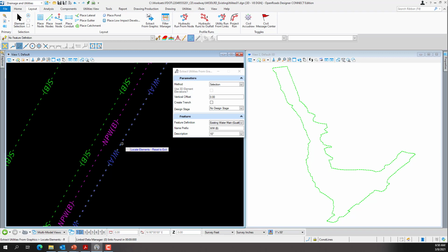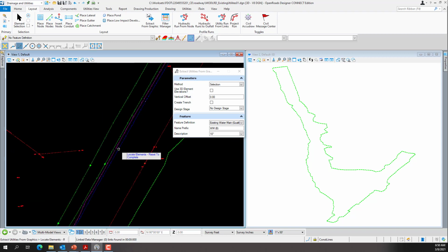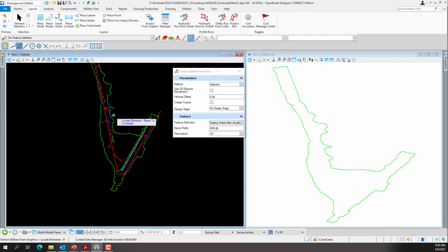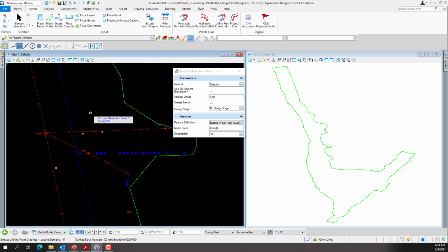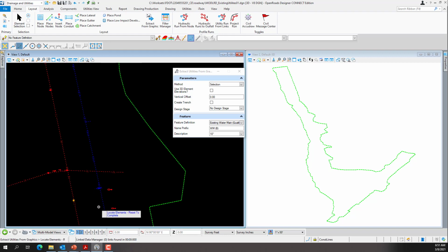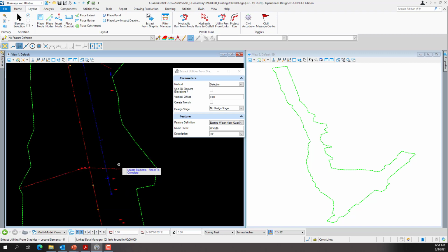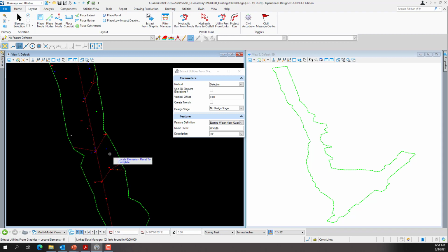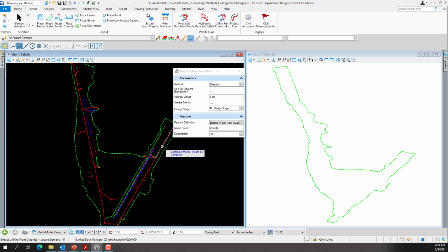So I'll click on the water line. You may have to do it one or two times. It'll tell you that the object is already in the current set. So I have this line, that entire line. Then I'll zoom up. There's more water lines over on this section. Okay, and a little tiny water line right here. And once you have everything selected for all your water lines, zoom out, zoom back in, just to verify and make sure I have all those lines. So I have this group of water lines and this group of water lines in there.